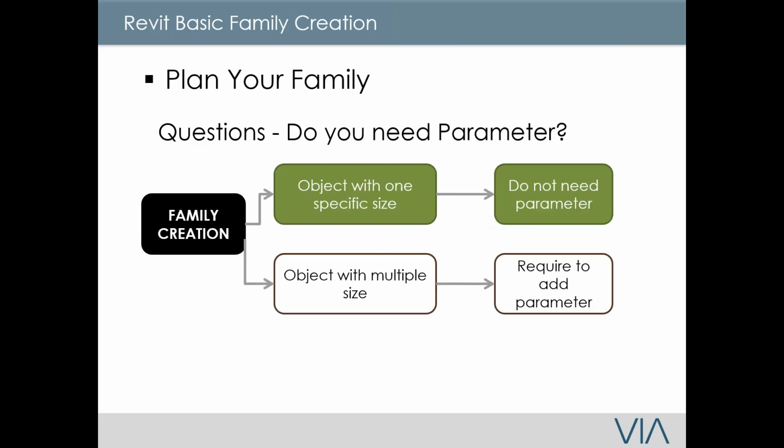Now, the question is, how do you plan your family? One question I always ask is, do you need parameters? Parameters will add file size. It's always going to create a very bloated file size. So what I typically recommend users to do is keep it as minimum as possible.